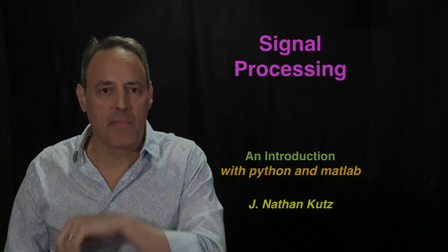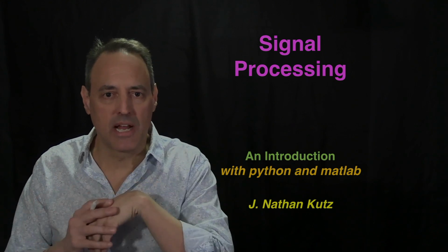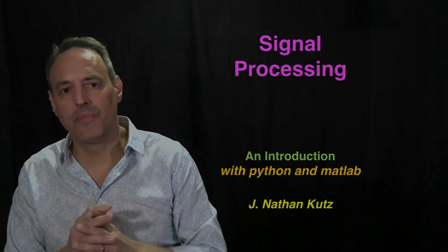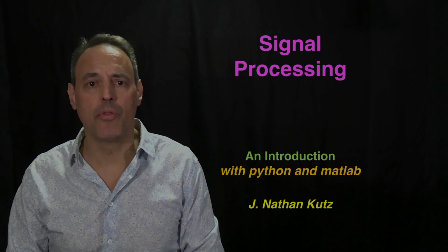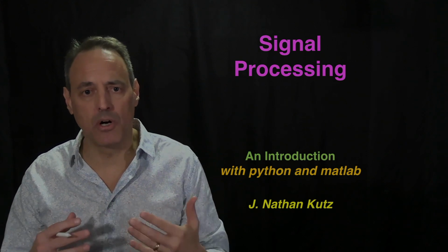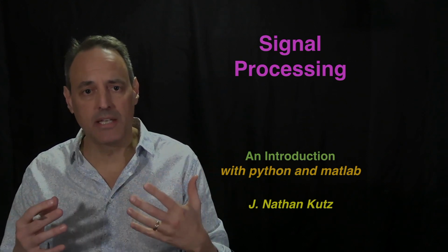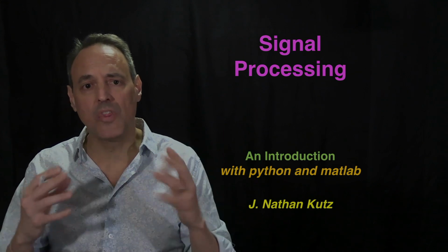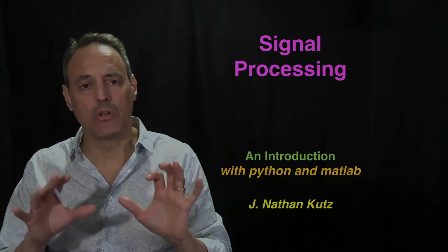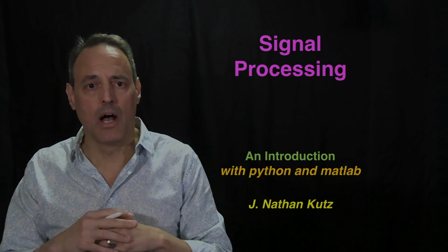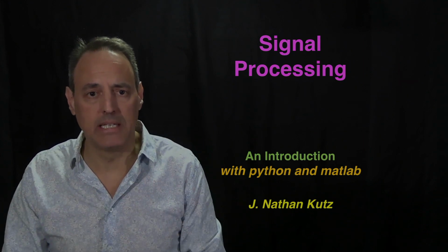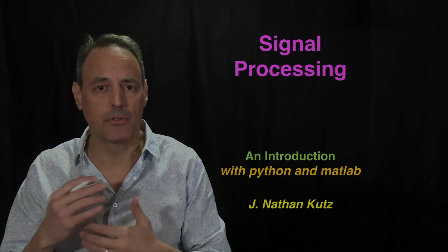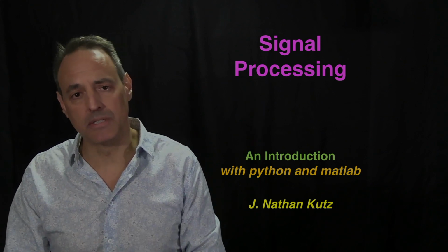We're going to continue talking about time and frequency analysis for signal processing, and I'm going to introduce the concept of what's called the Bode plot. The Bode plot is a way of understanding both the amplitude and phase response of a signal in an LTI system, and starting to rethink how signals look in this processing just by this very standard way of approaching it, which is this Bode plot idea, which both looks at amplitude and phase of the response of a system.